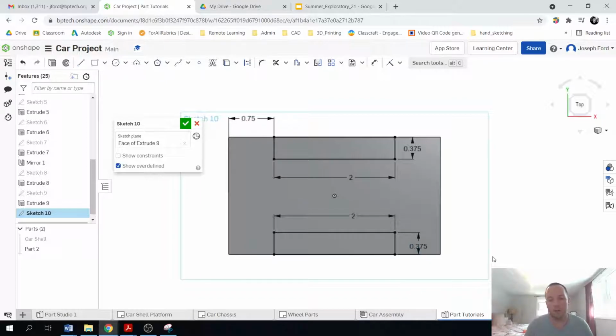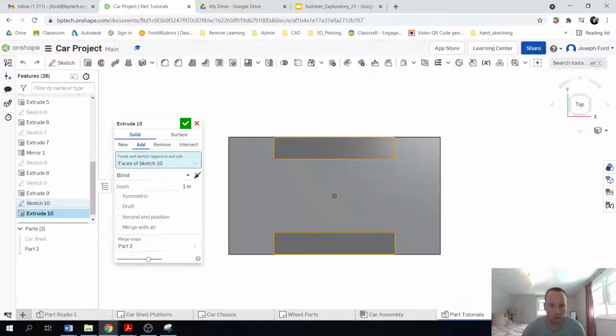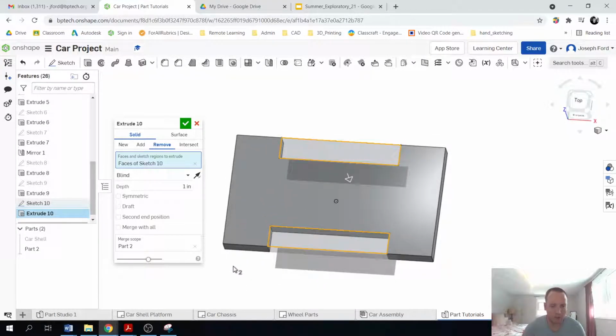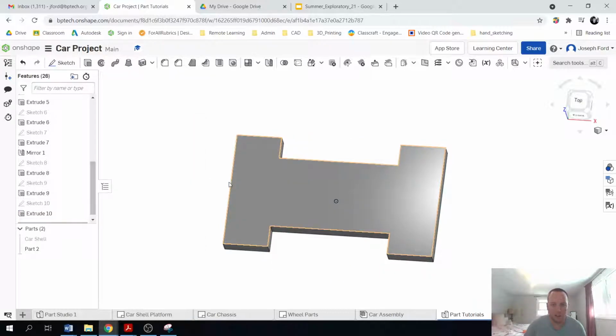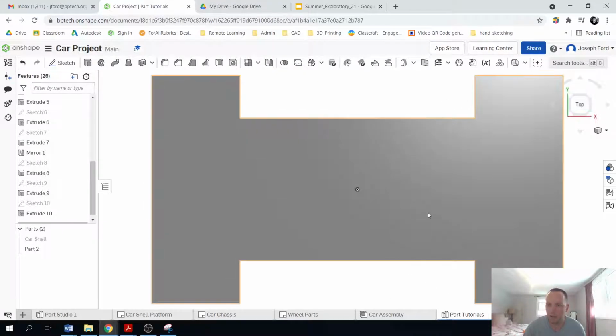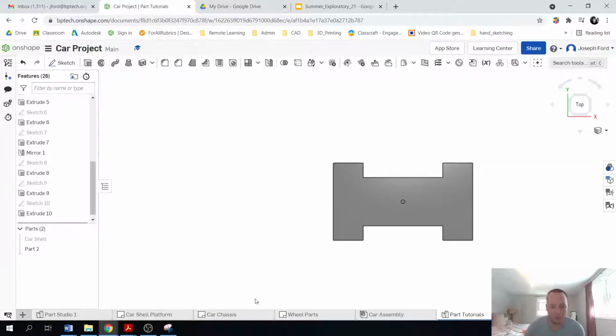So now we're all lined up here, and we're going to make these cuts. So extrude, and then remove, and make sure I'm removing in the right direction, and I am. So you can remove an inch in depth, but I would just get in the habit of removing the actual amount, and it's 1/4. So we're just removing 1/4. All right, that was easy enough.